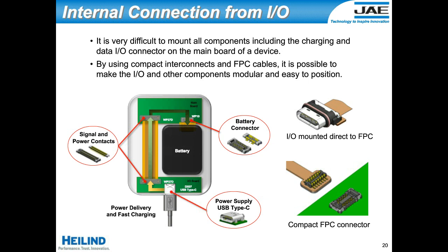Like we mentioned, there are a lot of height variations in USB Type-C available. However, to match every single specific case design, outer chassis design, and board placement is very, very difficult. Also, there are going to be a lot of applications or instances where other components, such as a battery cell, are placed right behind where the connector is mounted. That means you're going to have some type of cable connection from your Type-C I/O port back into your main board.